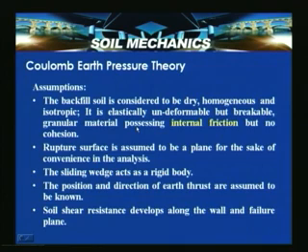Now let us look into some assumptions involved before discussing Coulomb's theory. The backfill soil is considered to be dry, homogeneous and isotropic, and it is elastically undeformable but breakable. It is a granular material possessing internal friction but no cohesion, so it is basically postulated for cohesionless soils. The rupture surface is assumed to be plane for the sake of convenience in the analysis.